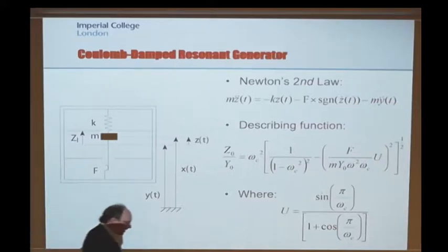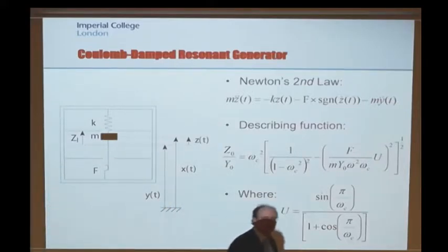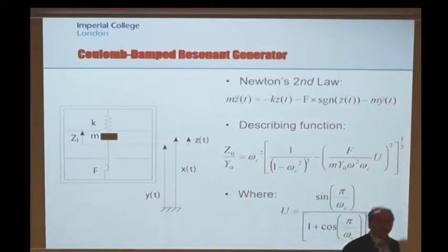I keep saying to you, I'm pitching this to you as the electrostatic implementation with the parallel plate sort of capacitor either moving like this or moving like this in constant charge. Actually, this particular damping type of regime is something that is actually operated also with piezoelectric harvesters, and the technique that Michael Lallart showed you yesterday with the flipping of the charge.